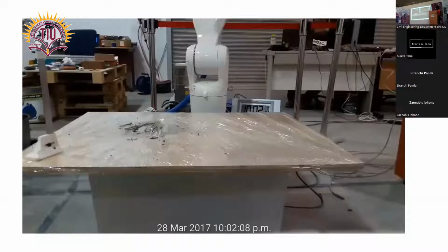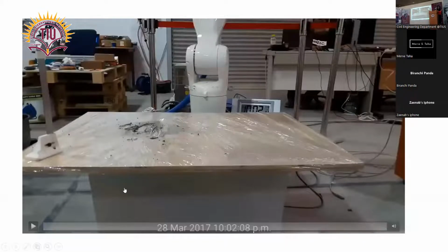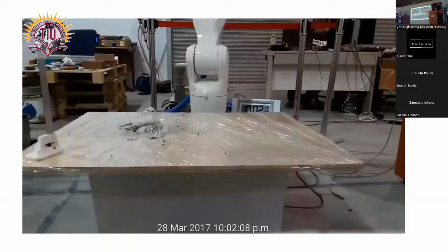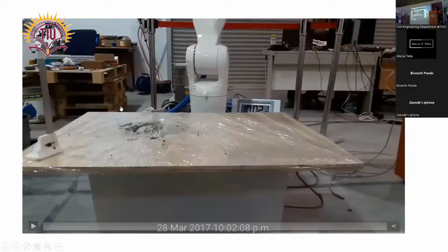So we also do some research on different geopolymer printing. Here is an example where we participated in a NASA competition to print geopolymer. The idea was to print with a small robot. We have developed a geopolymer material which is printable, and we have demonstrated, as you can see in this video, that the idea was to not have any small deformation during printing. We put a scale bar next to the printer, and during printing we try to see whether, after printing of 30 layers, we are getting any deformation, yes or no?